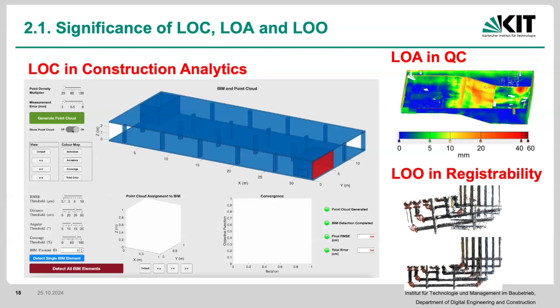But imagine if I'm collecting some images, once I'm doing that through a process called structure from motion, I need each and every one of these images to have some overlap. If they don't, it's kind of like me collecting some images here and then jumping and collecting some images here. If these don't have overlap, they cannot be registered. You can see it here. Okay, so the overlapping of objects, images, or anything else can help quite a bit, especially with automatic registration, because in order to register these together, you need some overlap between them.